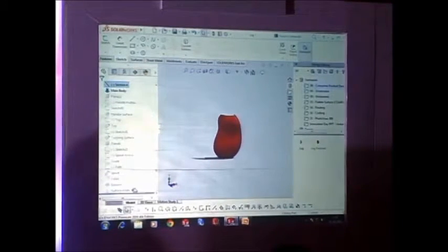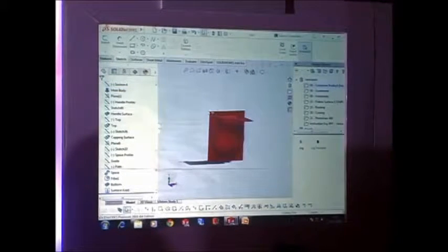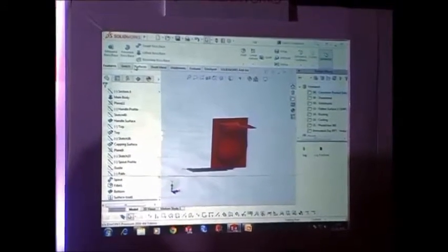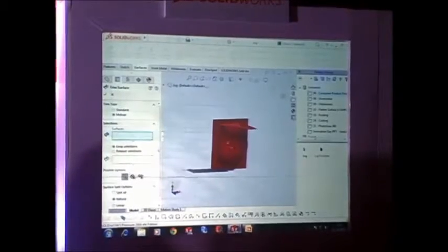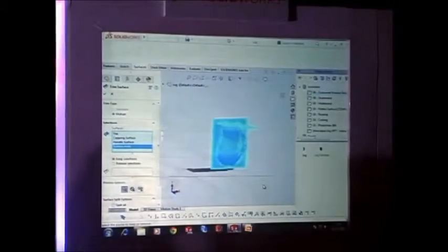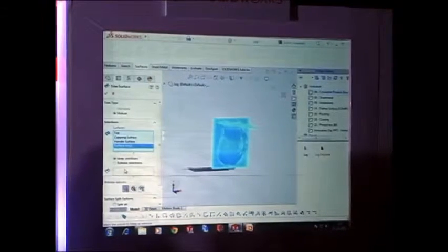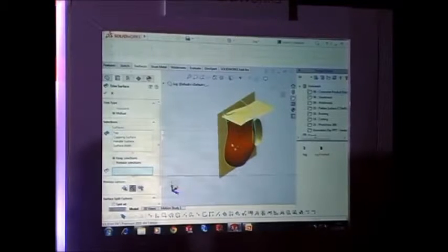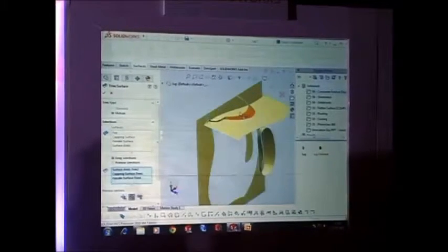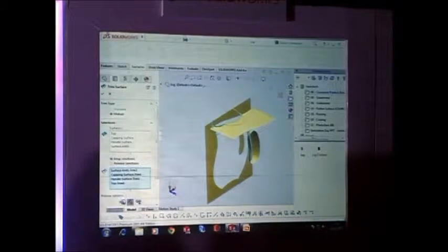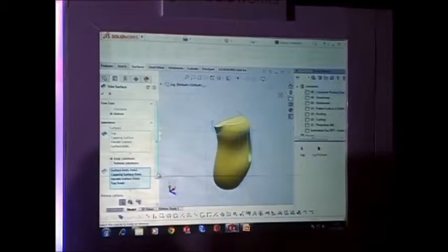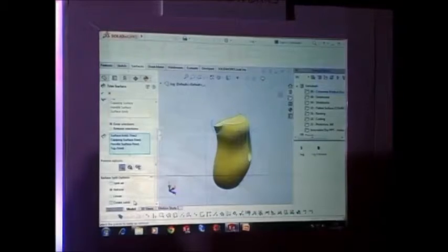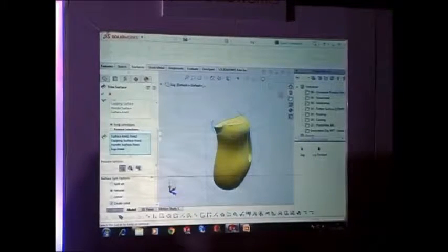Next, what we're going to do is get a true surface of this jug model. SOLIDWORKS introduced a new option in trim surface known as intuitive preview selections. Include, exclude, or both can be viewed here. So with less confusion, now we can easily trim our surfaces with less amount of time. Since it is a fully enclosed volume, we can easily create a solid here.